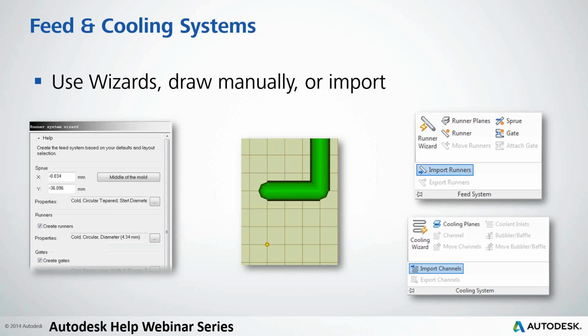Whenever you go to draw it manually, one thing to keep in mind is to use that grid pattern to help direct you to where you want to draw that runner. You can add options such as snap to grid, snap to runner, or auto connect to the next runner, and this will help make creating that runner more user-friendly.